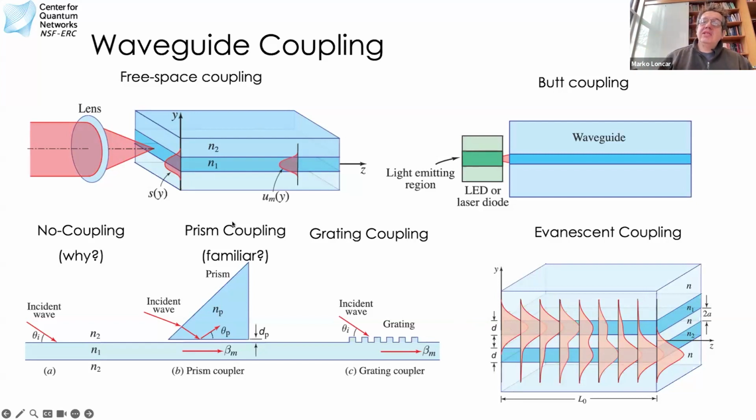And so all of these things that I discussed so far, and all the waveguides that I discussed, are so-called slab waveguides. So they're actually not very practical because they only confine light in one direction, right? In this Y direction here. In the Z direction, we don't want to confine light; light propagates. But in the X direction, light also can propagate. So it's not localized. This would be like a slab mode, light just covering the whole surface of your wafer. So this is not very useful because we want to integrate many components on the same chip.